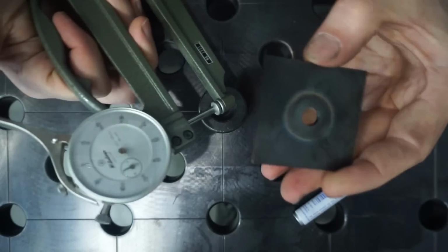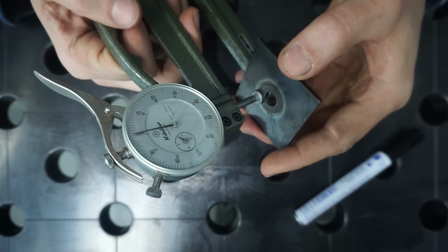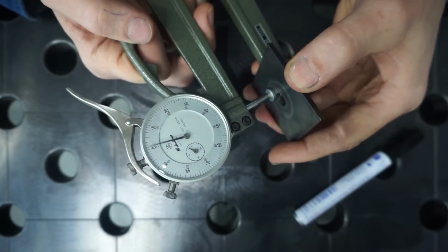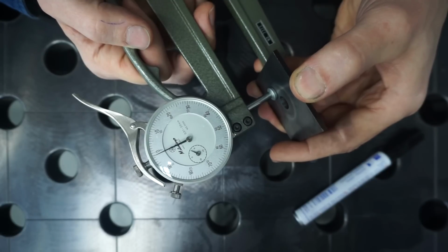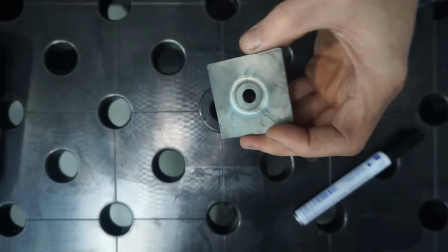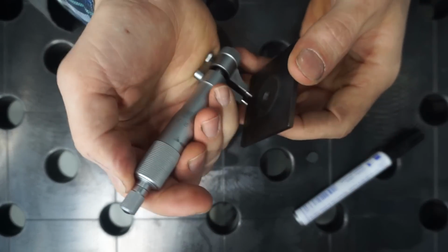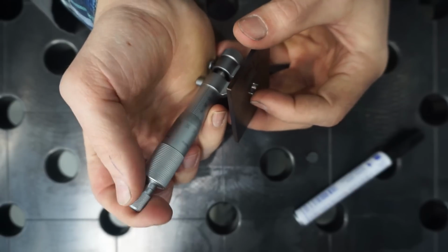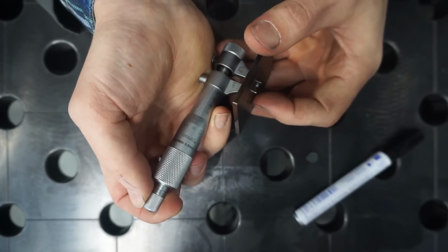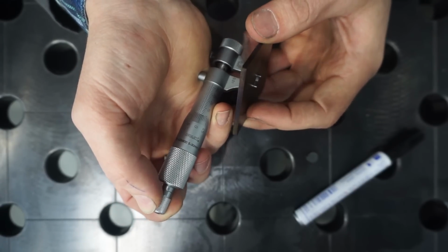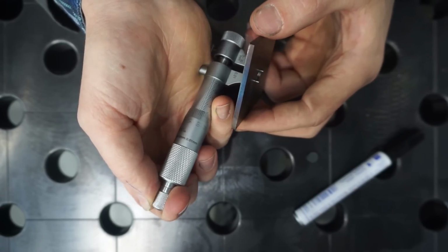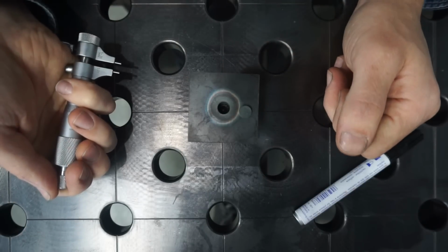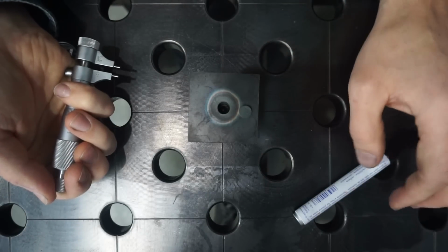The hole, on the other hand, let me check the thickness close to the hole. It was 2.98, it's 2.99, so that almost didn't change. And the hole diameter was 10.02 and now is entirely unchanged. So the deformation of the plug proves the plastic deformations which we discussed before.